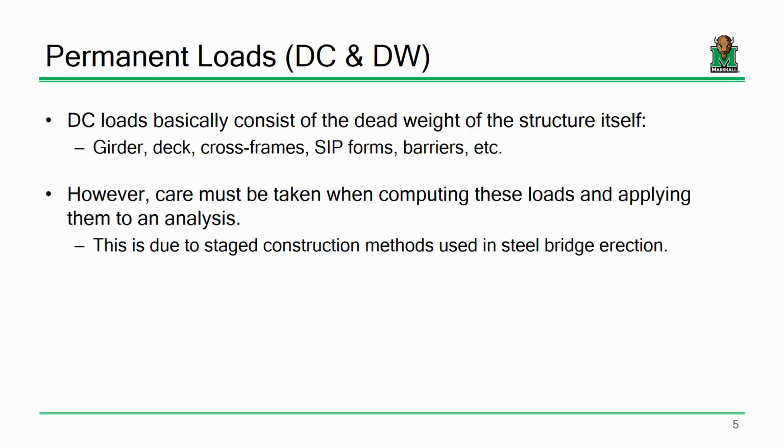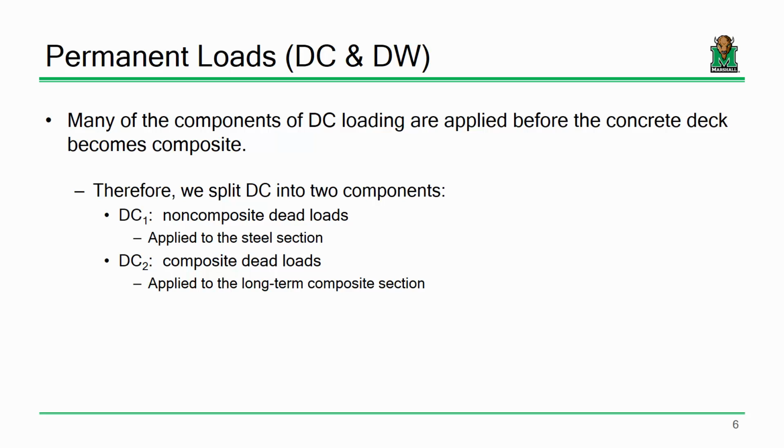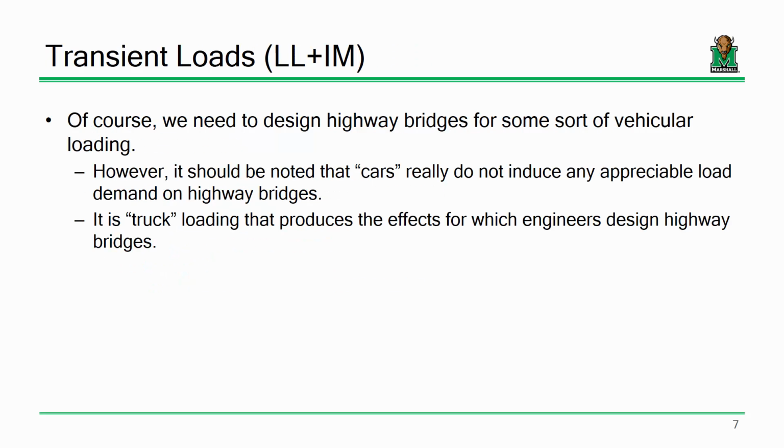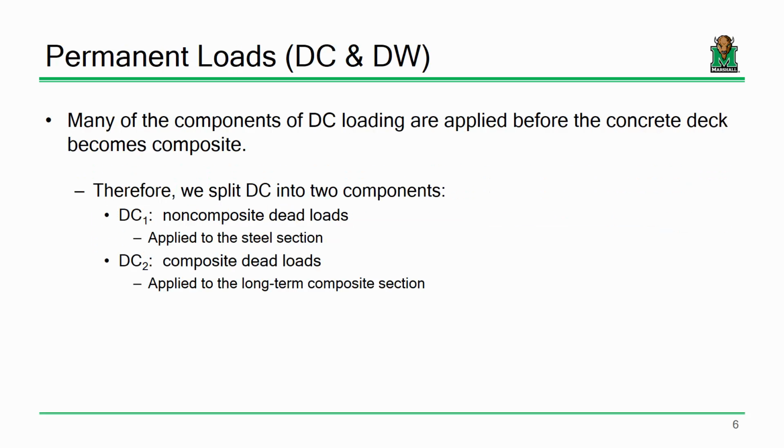Now, there really wasn't a whole lot to say on permanent loads. It's just the self-weight, pretty basic stuff, really. I mean, take the unit weight of a material, multiply it by the area to get a weight per foot, stuff like that. And a lot of the load computations that we did for dead loads fall mainly on common sense, just pretty basic ideas. As long as you're keeping track of units and you're just assuming all the load gets equally distributed to each girder, it's not tough. It's pretty straightforward stuff. So there really wasn't much discussion about the dead loads other than they're there and we need to compute them.